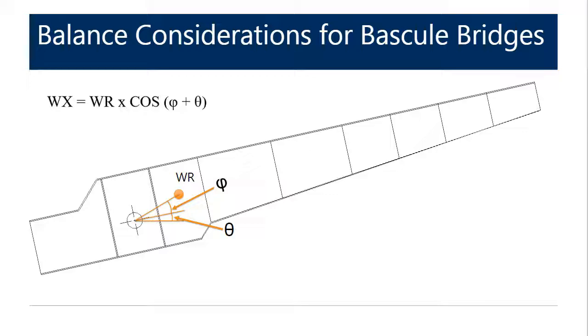And performing balance calculations is a good idea as well, to understand whether the new grading is significantly lighter than the old, et cetera, to understand what kind of impact your new grading will have and what kind of balance adjustments you'll need to make to your counterweight. And additionally, strain gauge testing can tell you at the end of the day exactly how much weight to install or to remove from a counterweight.